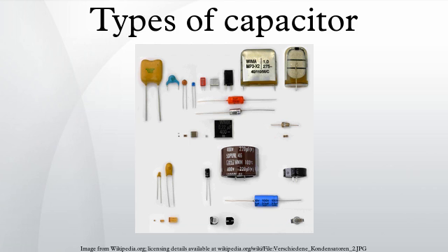Class 1 ceramic capacitors have an insulation resistance of at least 10 GΩ, while Class 2 capacitors have at least 4 GΩ or a self-discharge constant of at least 100 s. Plastic film capacitors typically have an insulation resistance of 6 to 12 GΩ. This corresponds to capacitors in the µF range with a self-discharge constant of about 2000 to 4000 s. The self-discharge constant can be reduced if humidity penetrates into the winding. It is partially strongly temperature dependent and decreases with increasing temperature. Both decrease with increasing temperature.